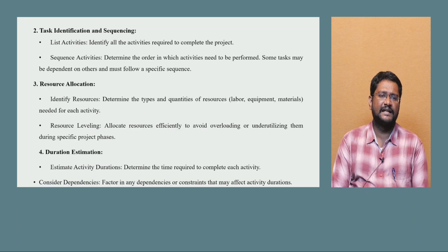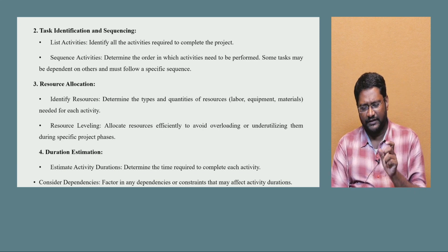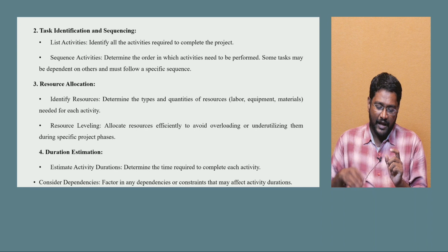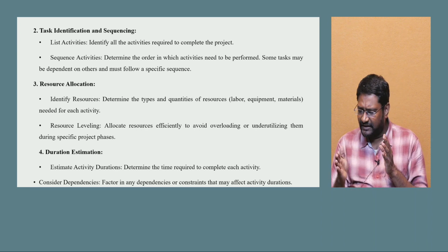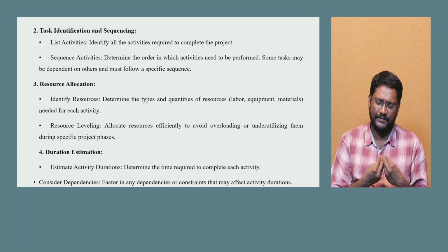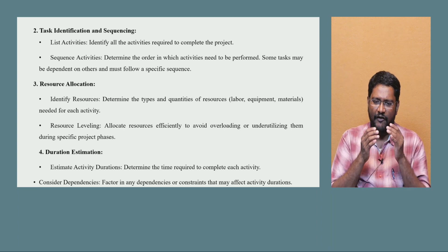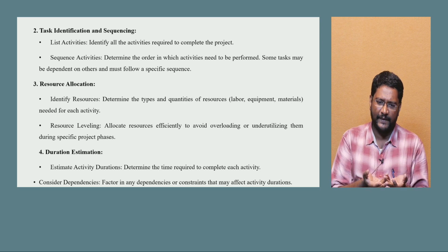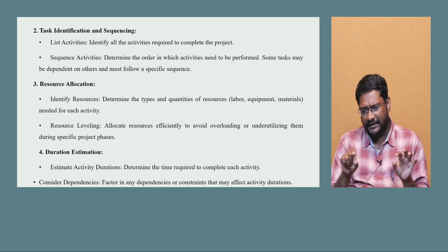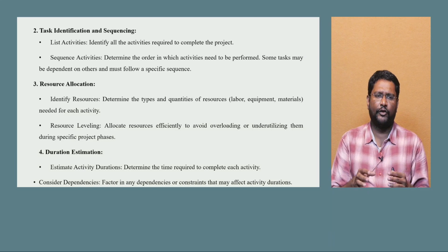Second step is task identification and sequencing. For example, first we have to identify which task has to be completed. After completion of this task you have to go on with the sequence only. For example, after laying the plain cement concrete you have to lay the piles. After the pile cap, connecting it will be the grade beam, that means plinth beams, and that has to follow the sequence only.